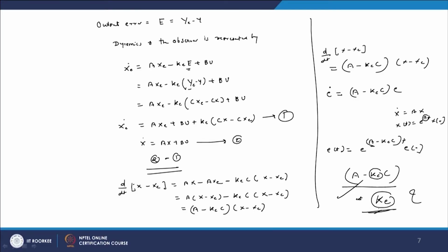That is why here we have taken the K matrix, the error between y and y hat. Here the K plays an important role. Because the eigenvalues depend upon the subtraction A minus KC, when the eigenvalues are far away from the imaginary axis, the error reduces to 0, and this depends upon this K matrix.